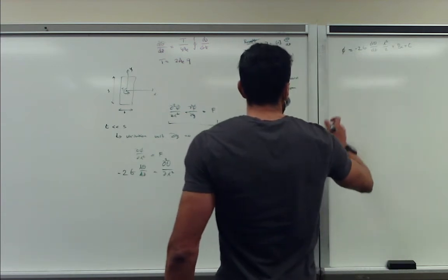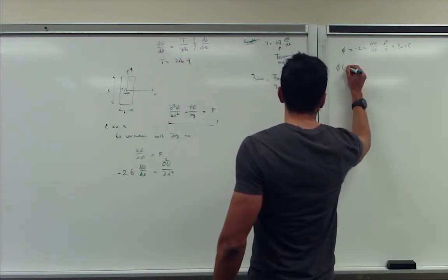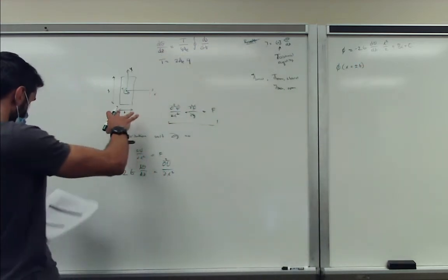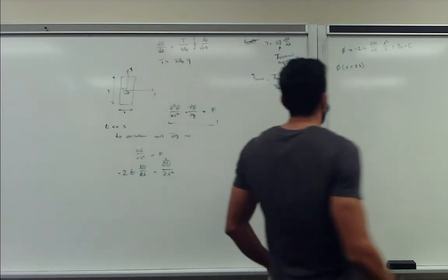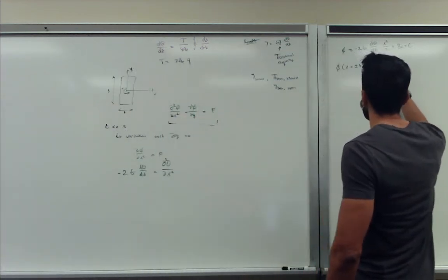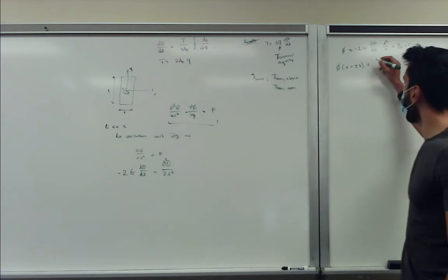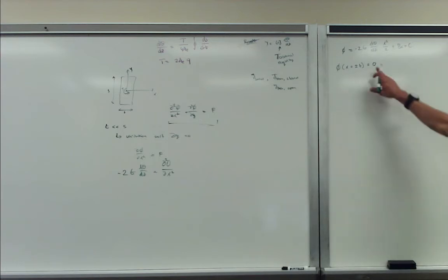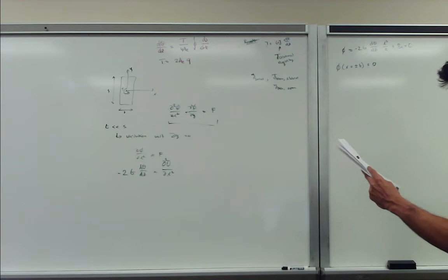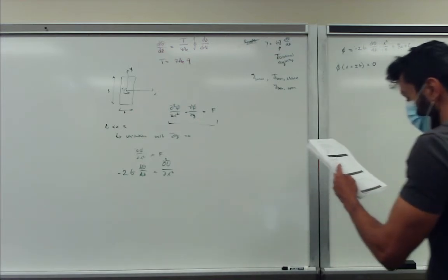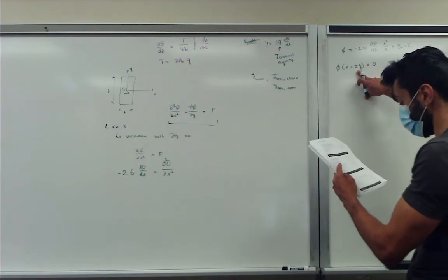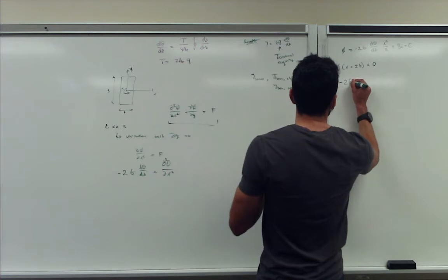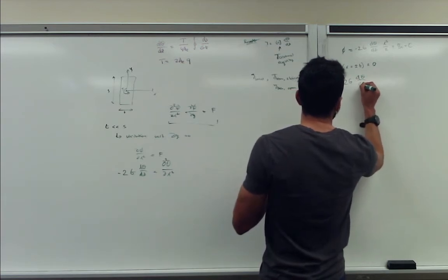And then we look at the boundary conditions. We look at phi at x equal to plus or minus t over 2, so basically at these two locations. We know at these locations, since it's extremely small, we will not have any variations and no stresses at the boundaries, so these two must be equal to 0. So what we can do is just plug it back in. We'll get plus t over 2 and minus t over 2.